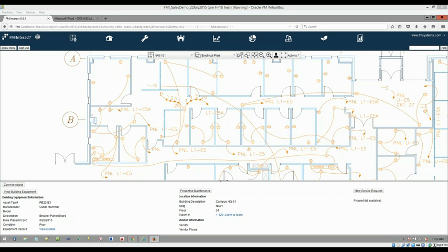The next question, are the manuals available in FM systems because it was obtained by BIM, or is it because they were manually copied into the database? Yes, it would be the answer. So you can manually upload these. The ideal situation is, yeah, we have that Revit model, we have all that information, we have the documents, and we know what piece of equipment they go into, so we can automate that process. So you're not having to add these in one at a time. So we can definitely go through a couple different ways, but automate the process of adding in those documents.